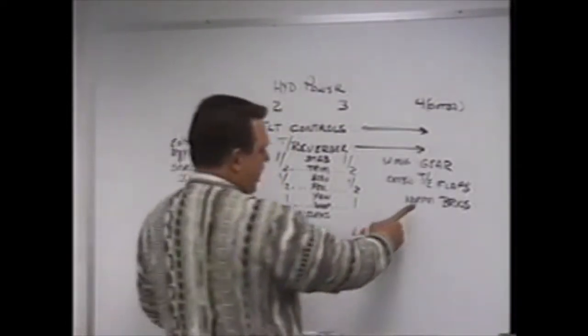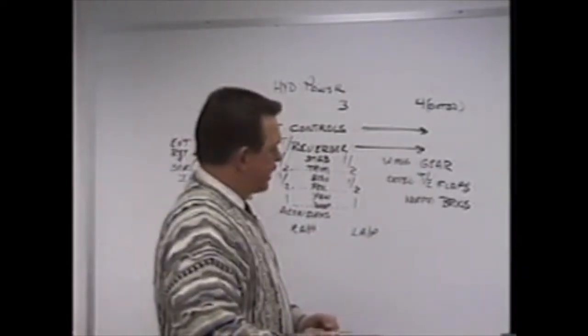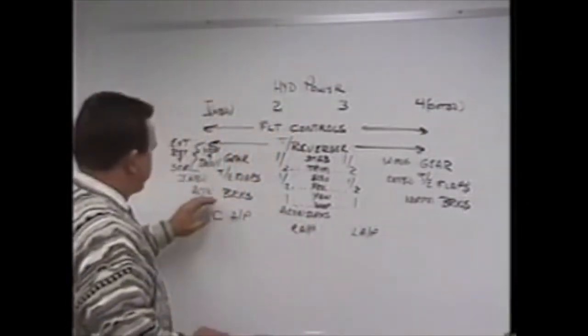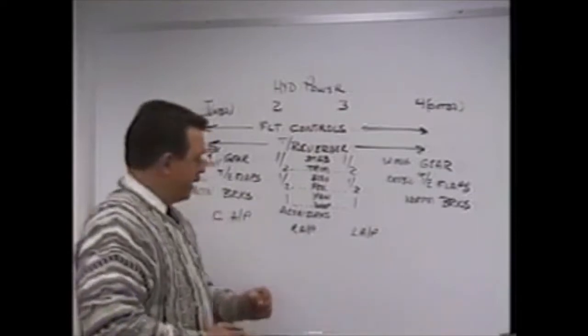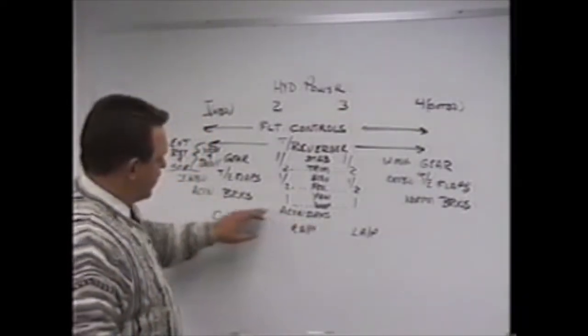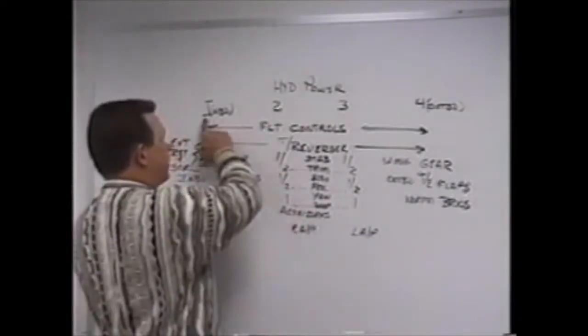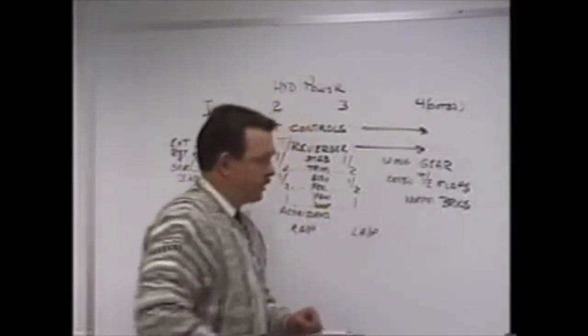Normal brakes has anti-skid, a very elaborate individual wheel anti-skid system. It also has auto brakes. The alternate brake system has anti-skid, but it's not as elaborate. It's paired up in axles. It does not have auto brakes. Alternate brake system is identical to this brake system. The only difference between these two systems is which system pressurizes it. This system is entirely different than the normal brake system on System 4.